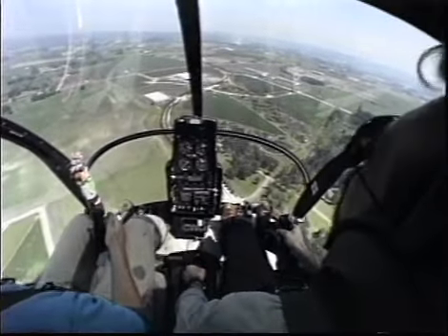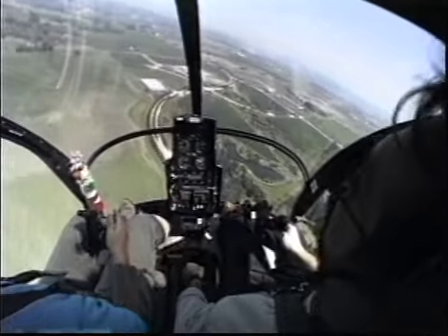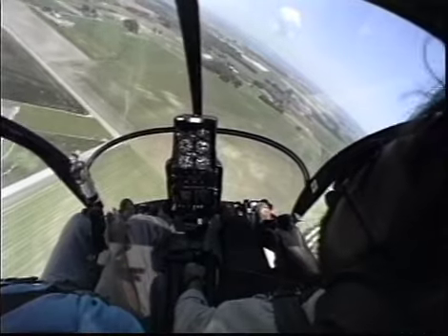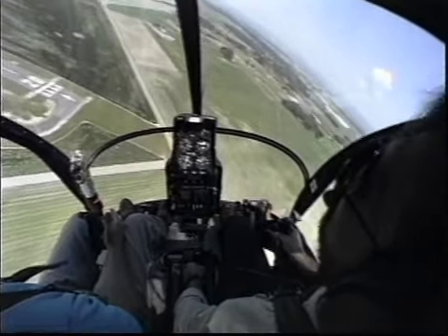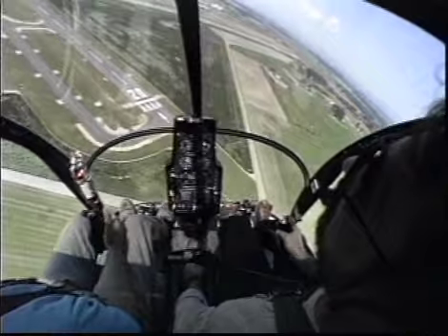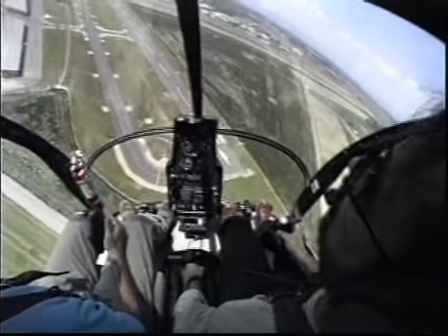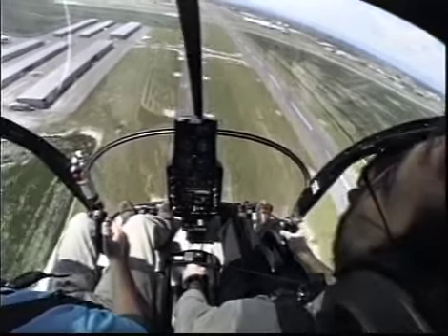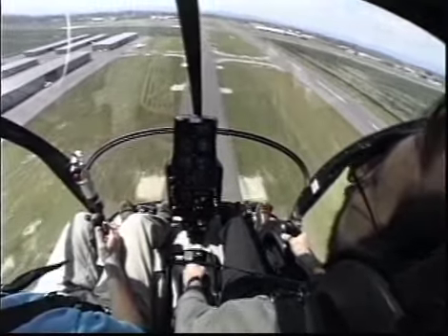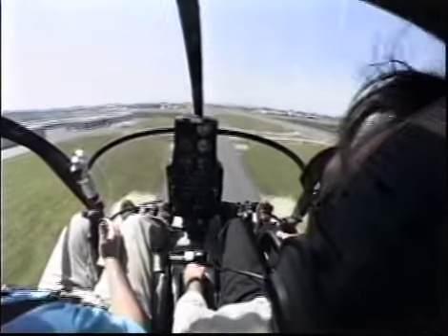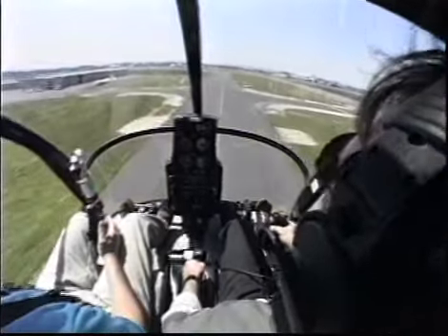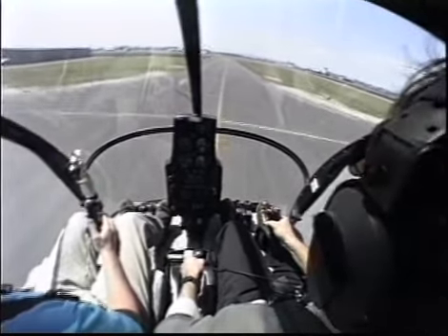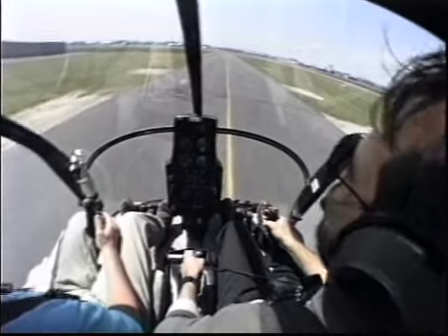The FAA recommends entering autorotation if an anti-torque failure occurs during forward cruising flight. Keep cyclic control movements to a minimum until all pitching subsides. If sufficient forward speed is maintained, the fuselage remains fairly well streamlined. However, if you attempt a descent at slow speeds, you should expect a continuous turning movement to the left. Maintain directional control primarily with cyclic control, and if necessary, by gently applying throttle momentarily with the needles joined to swing the nose to the right, or decrease the throttle to swing the nose to the left.